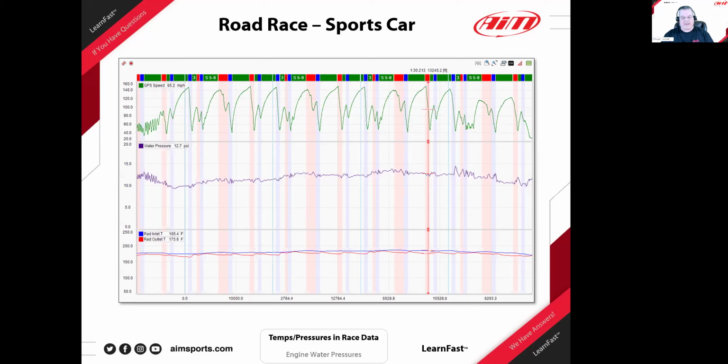will be super valuable. So if you ever have a hose that breaks, or a pinhole in the radiator, or even a cap that goes bad, this pressure that's just bumping along at, this is probably a 13 psi cap on the radiator, is sitting there right at 13 or so once it gets warmed up and everything is going well. And if he were to get any leak in a radiator or a hose or anything, this would drop immediately down to zero, the pressure, even though the water is still in there for a while. And you can set an alarm on your dash, and if the pressure goes to zero, you really need to understand it and determine what you want to do.